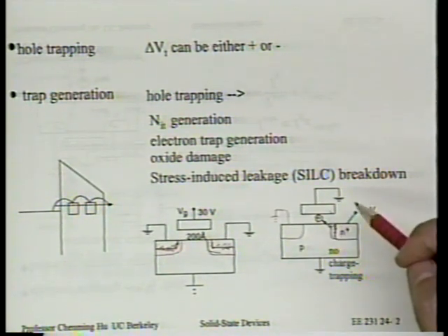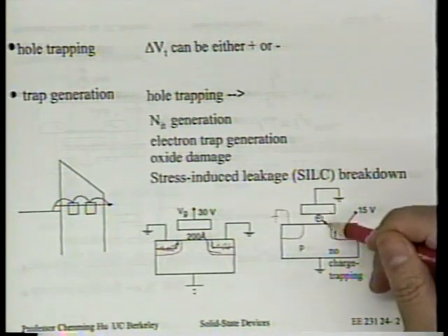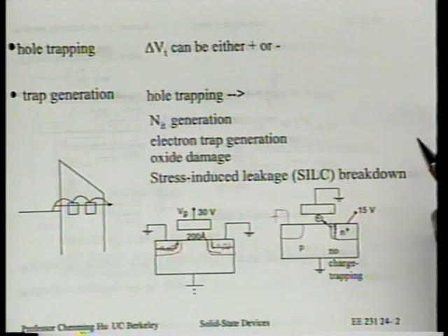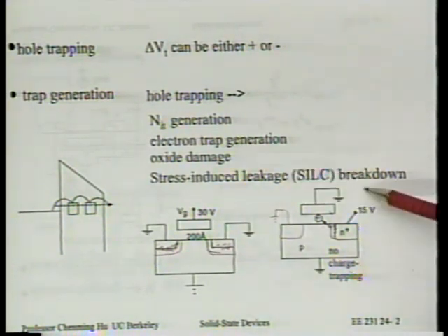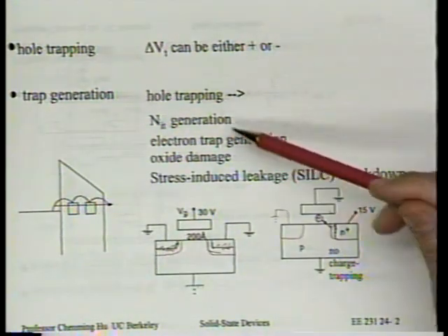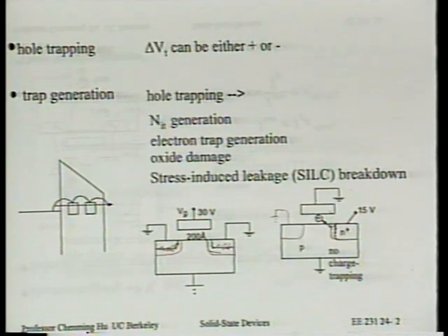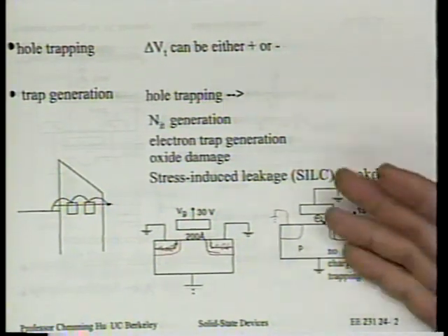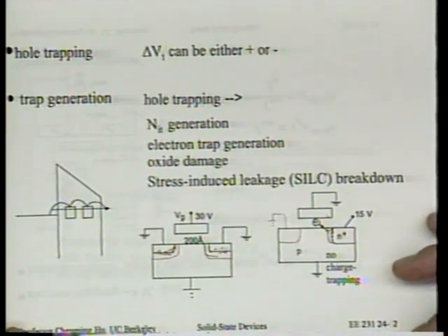But what's interesting is that not many people know that when you inject a certain amount of holes, oxide just breaks down. So this just goes to show you that there is substantial evidence that breakdown is a result of hole generation or hole trapping. Okay, there is other evidence like that. And by the way, people have patented this as a way of breaking down an oxide.